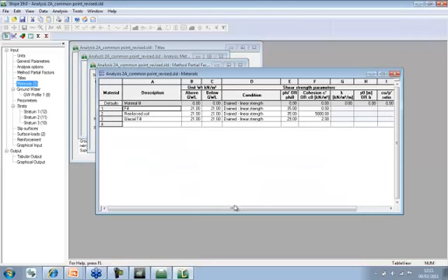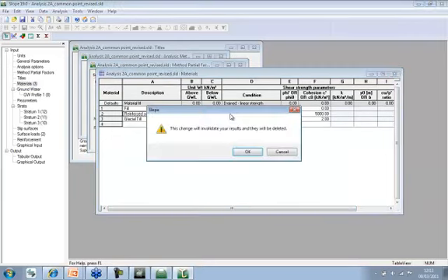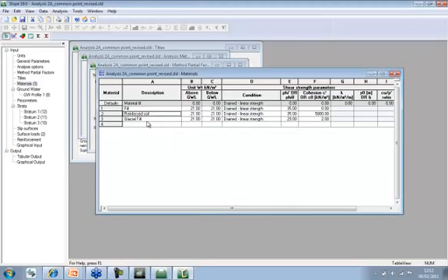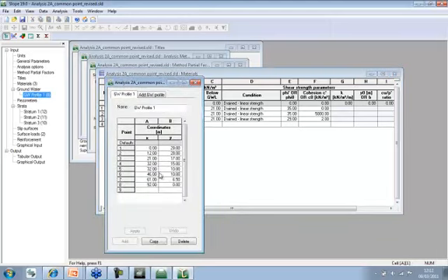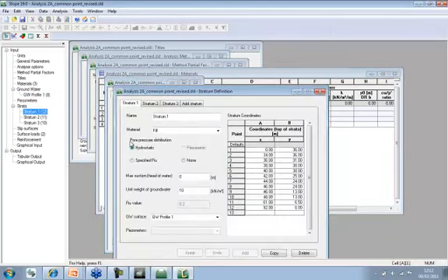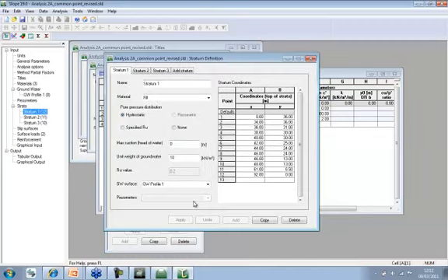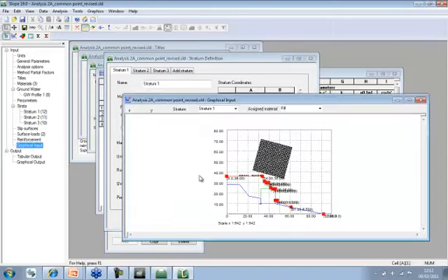And of course there are the material properties, which are put in here for fill, reinforced soil, which represents our reinforced soil block, and glacial till. We've got a groundwater profile which has been set in. It's variable, and for each stratum we can give information about the pore pressure distribution, and we can also give the actual details of the strata either through a tabular input, as is shown here, or through the graphical input.